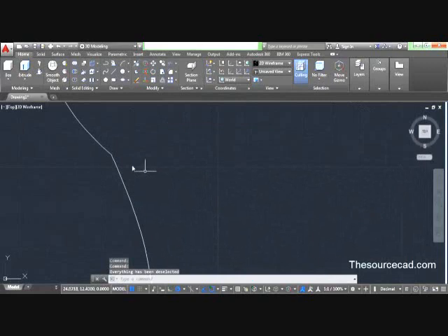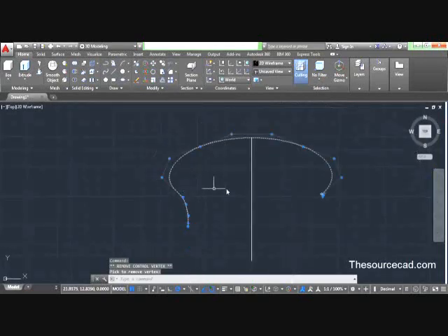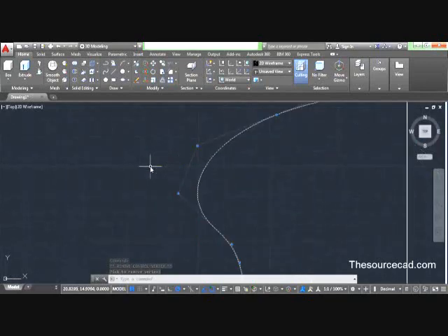Now select it again and we'll remove this sharp corner. Select it, go to this corner but don't click, and select this. Now you can see that the sharp corner has been removed. We have the previous spline. Now let's go and manipulate it a little.